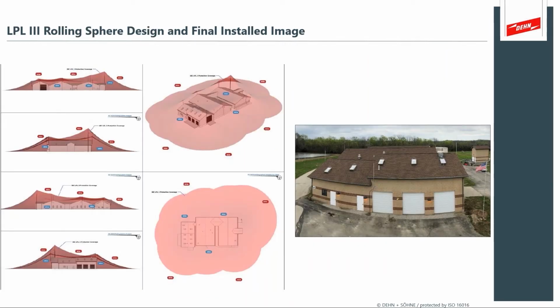So we've established the earthing, and now we want to take a look at the actual air termination and down conductor system. And these are a couple of really nice models that show the placement of the air terminals to create a rolling sphere design that will offer suitable protection over the water control system, the water process buildings. And in the photograph to the right, we can see the lightning air terminals around this structure, the finished result with the down conductors meeting into the soil.